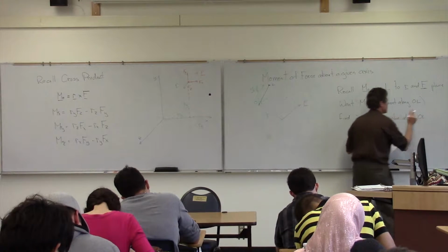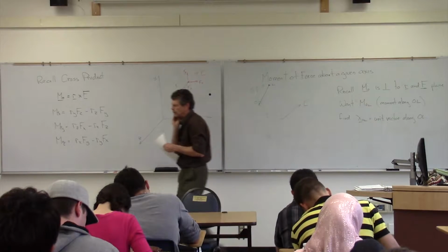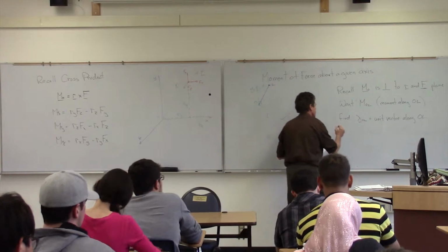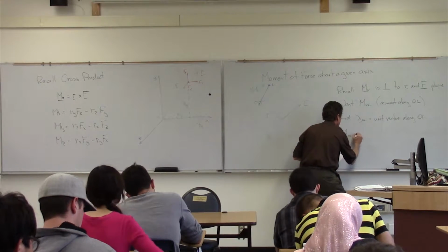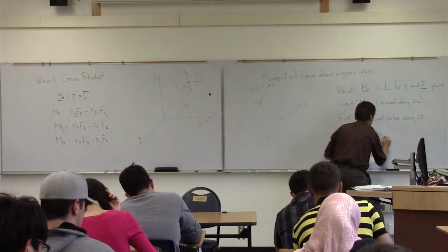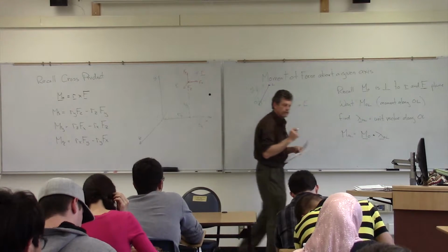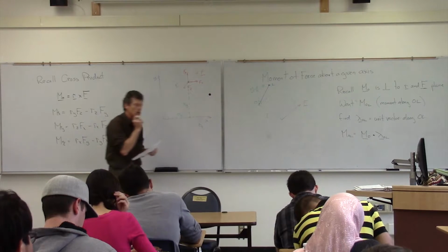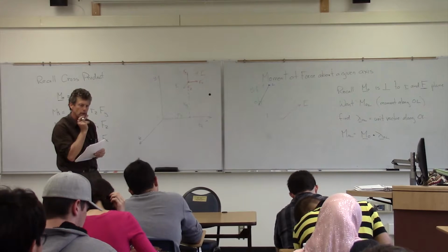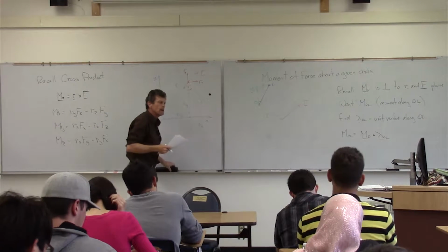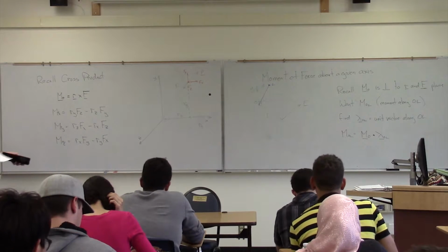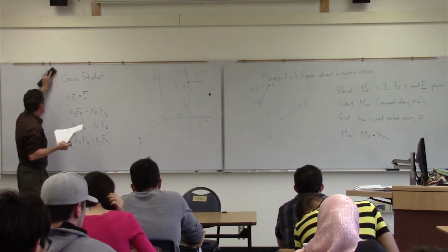What we're going to do is then go back and find a unit vector. We're going to find a unit vector along that OL. And what we'll find then is that we can find the magnitude of that moment about that line, OL, by this weird little thing called the dot product. And I'm sure you're all read up and caught up on that. But again, this is the second way you can multiply vectors. We did the cross product, the more complicated one. This is actually a very easy one.